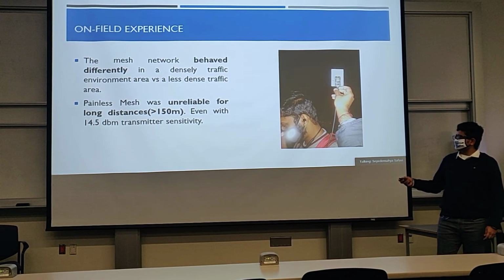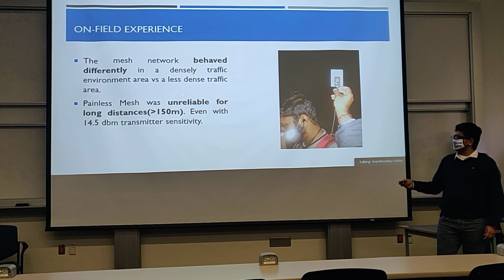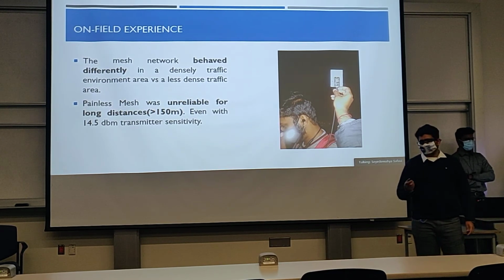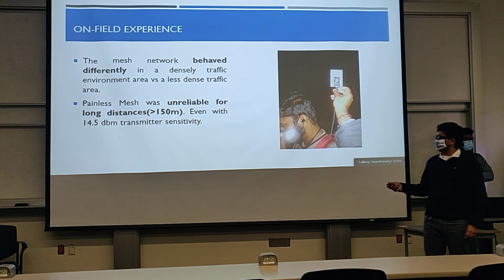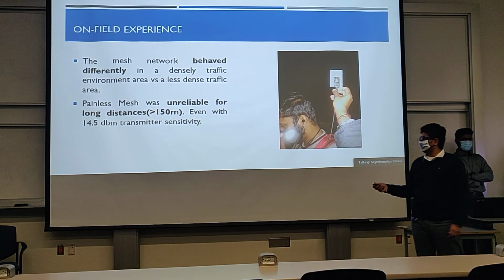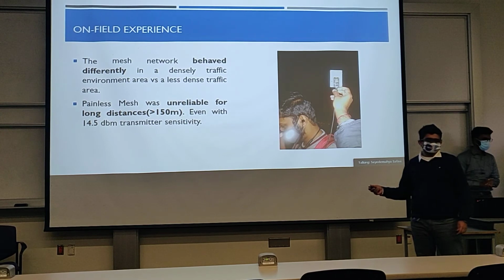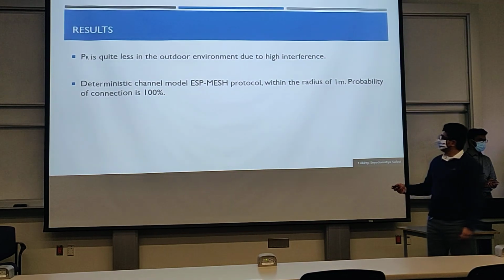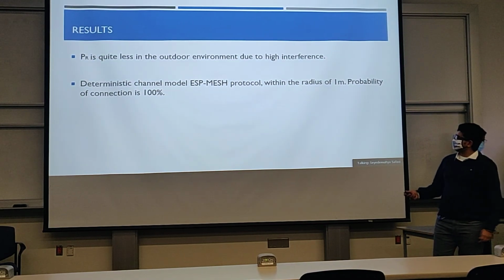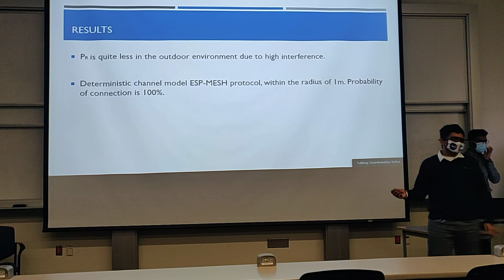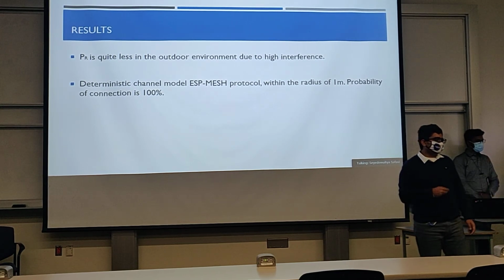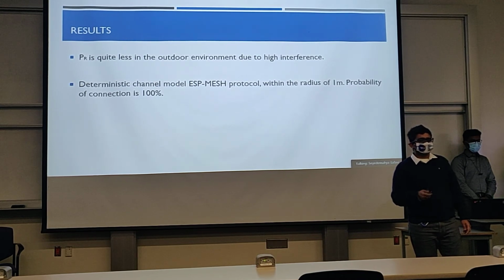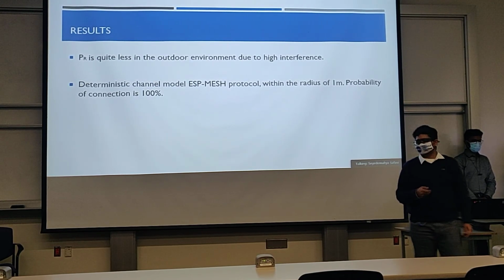Then we moved to a less dense traffic environment, and we saw that the ranges we were getting from a point-to-point LOS connection were about 150 meters at 14 dBm transmit power, which is the maximum for this particular ESP. The other thing we found was that this particular model can only be used for indoor applications, because the range at max is somewhere around 50 meters, where you would get a good, reliable connection.